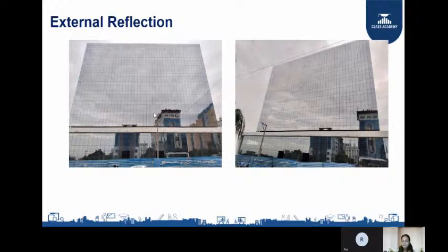You just multiply it with the SHGC of the glass. You will get the total direct heat per square meter. And for total indirect heat, you just multiply whatever temperature difference you have inside and outside with the U value of the glass. I'll give you one example so you can have a better idea here. And it will again tell you why SHGC or solar factor is important.